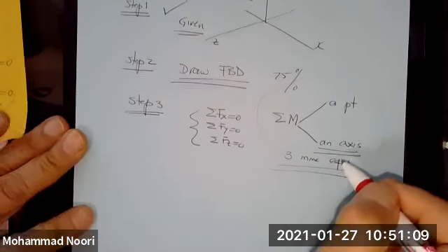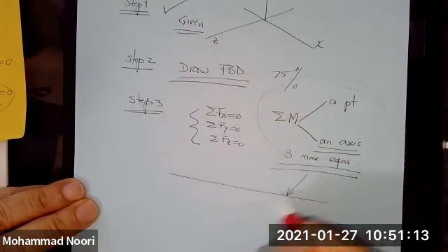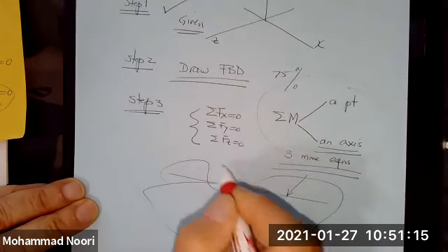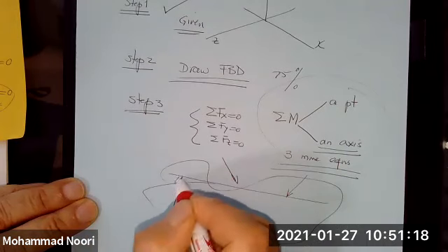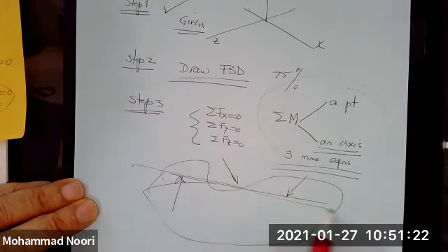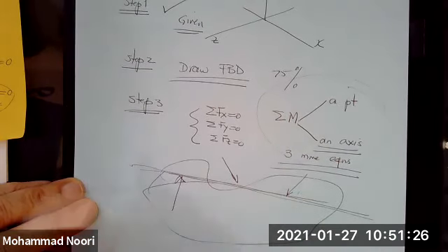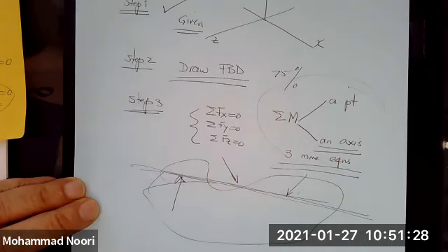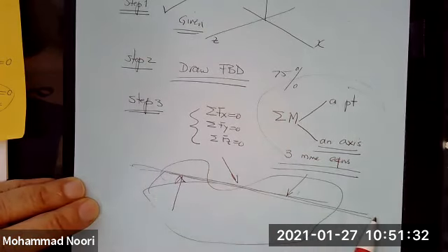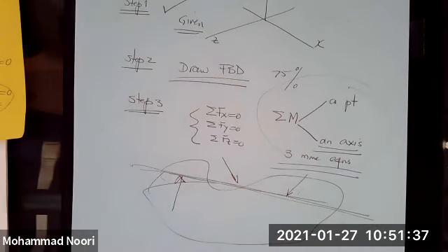The only difference between these two is, if you have a 3D object and you have forces acting on this object in such a way that you can find a line that intersects with some of these unknown support forces, if you take summation of moments about that axis, you can get rid of these unknowns.